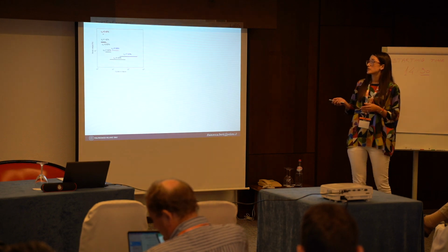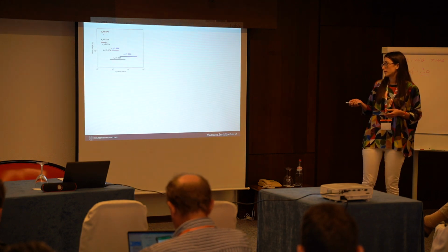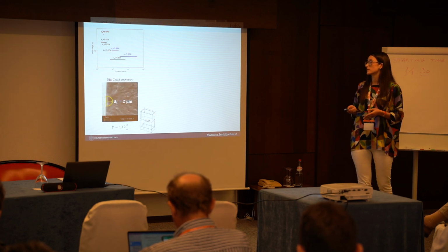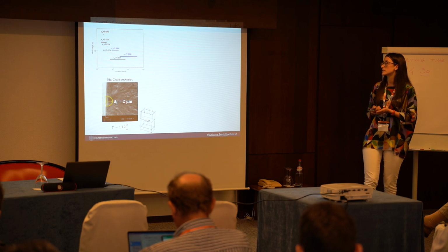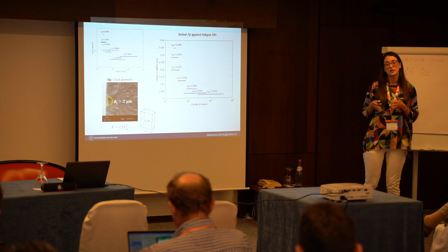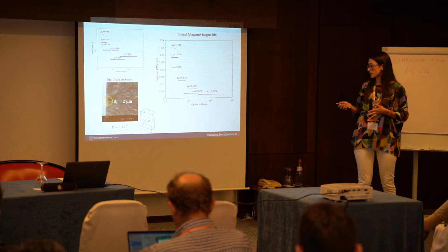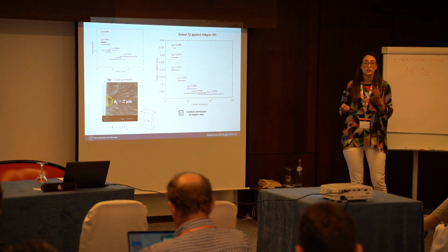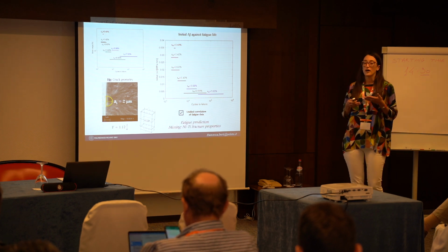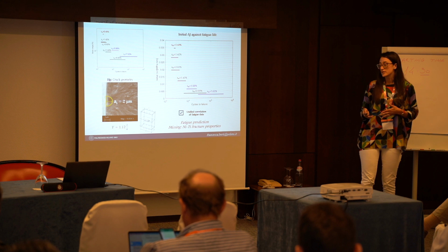So, as a first proof of concept, with the strain life diagram, we made the hypothesis of a crack of 2 microns, and just plotting the initial value of the cyclic J integral against the fatigue life, you can see we obtain a much better correlation. But we are not happy about this. We wanted to perform an effective fatigue prediction of these results.